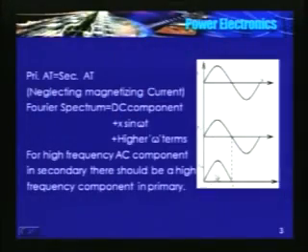The output voltage across R is a half wave rectified waveform. The load is purely resistive, so the current waveform is also half wave rectified. Current flows in the load from 0 to pi.